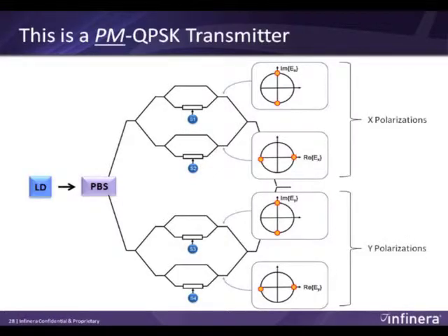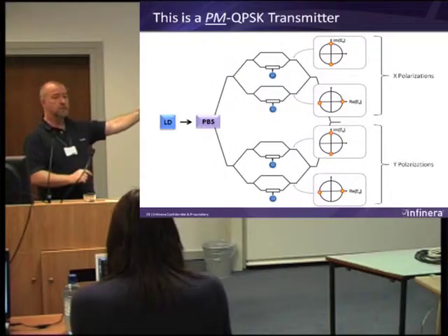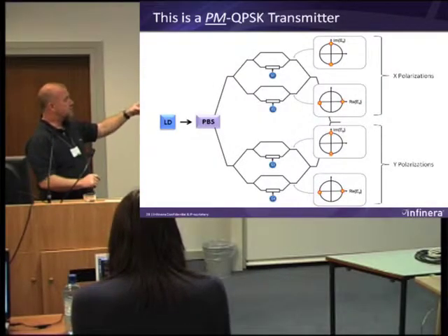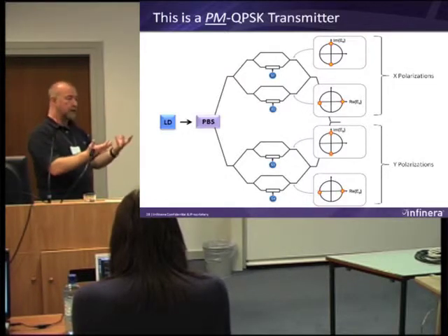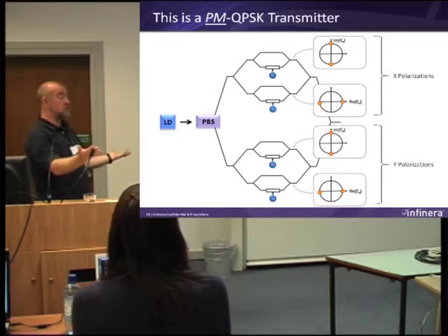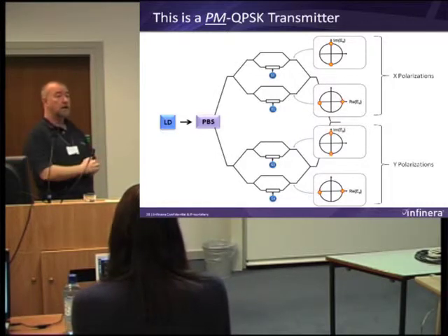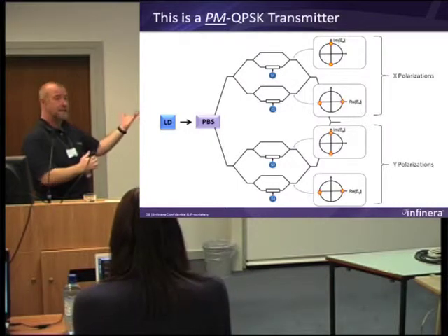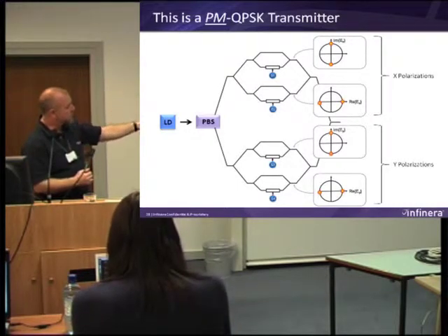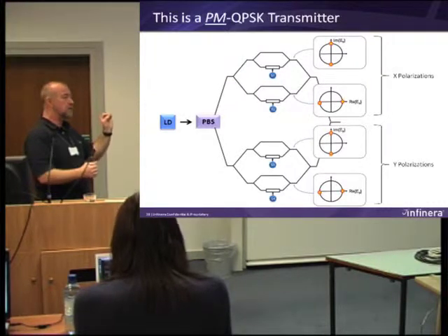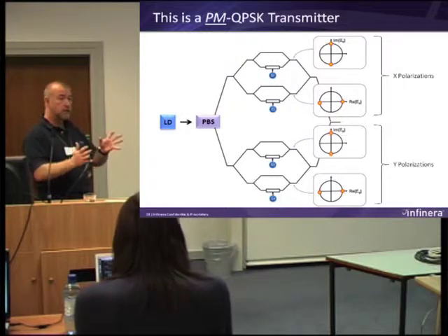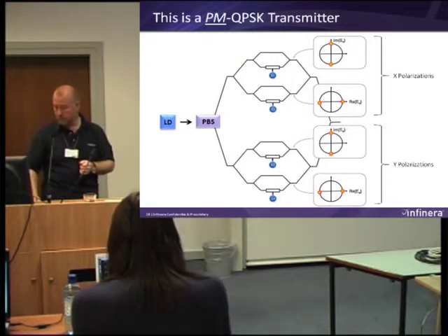Well, that is currently the state of the art in terms of 40 gigabit transmission. That's a really good modulation technique. One of the reasons it's very attractive is that it operates at 10 gigabaud. It's the same baud rate as 10 gig NRZ, so you have the same design rules in terms of optical reach as you would at 10 gig. Fantastic. Also, you'll notice the 4 signal inputs, the little blue blobs, each of them runs at 10 gigabits per second. And 10 gig electronics is cheap. So this is a very attractive implementation.